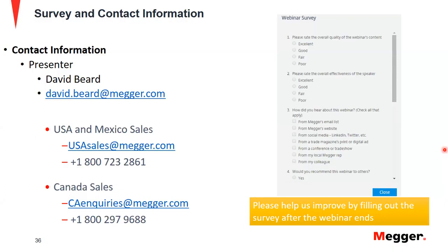Once you get that run, it gives you an option at the top by the report that says add to report. If you're in the timing screen or one of our predefined screens, like a transformer differential screen or a state sequencer, those automatically populate that test into a test file. As you were looking, I went into the T with the lightning bolt, which gives me my different tests and allows me to group those tests how I see fit.